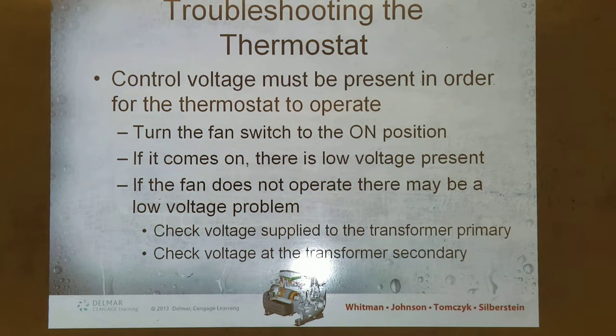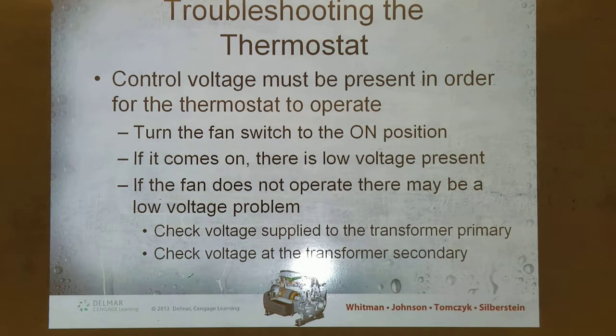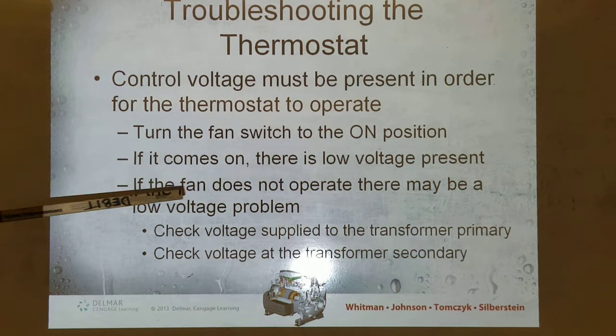Let's assume yes, control voltage. If the fan doesn't come on, then you know you have a problem with control voltage or high voltage, either way. All that's going to do is turn on the fan with the switch in the on position. If it comes on, fine. If it doesn't come on, it's going to take you to the high voltage or something else.